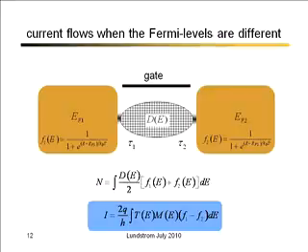So the electrons that come in from the source, they all have positive velocity. So they can occupy positive velocity states in the channel, plus k states, say. So they can only occupy half of the states. So it's like Professor Dada's freeway: half the lanes go one direction, half the lanes go the other direction. The electrons that come in from the source, coming in ballistically, can only occupy the positive velocity states.